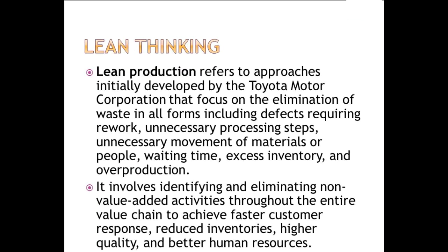Lean thinking. Lean production refers to approaches initially developed by the Toyota Motor Corporation that focus on the elimination of waste in all forms, including defects requiring rework, unnecessary processing steps, unnecessary movement of materials or people, waiting time, excess inventory, and overproduction. It involves identifying and eliminating non-value-added activities throughout the entire value chain to achieve faster customer response, reduced inventories, higher quality, and better human resources.